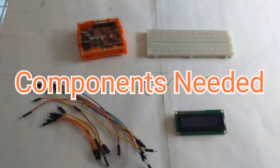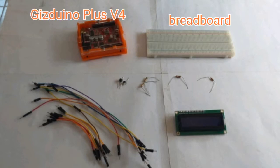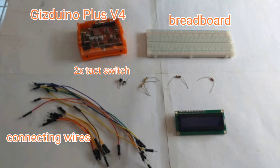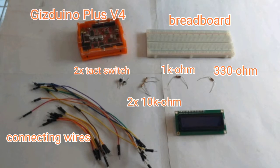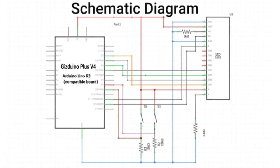What are the components needed? So we need to have our microcontroller board or breadboard, connecting wires, 2 pieces tact switch, 2 pieces 10 kilo ohm resistors, 1 kilo ohm resistor, 330 ohm resistor, and our 2x16 LCD module. And next, for the schematic diagram.